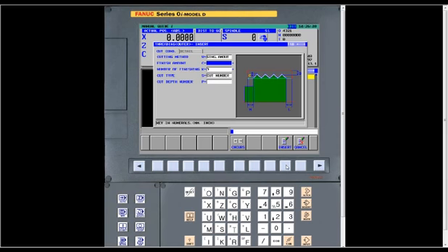The finish amount, you can leave a particular amount of finish stock or a particular number of finishing passes. And then also you can have cut type. You can have number of passes or depth of cut. Those are your 2 choices. I'm an old engine lathe guy, so I'm used to cut number. I've got in my head how many passes I want to take, so I always use that. But some people always think in depth of cut. That's all right, too. It'll work both ways.